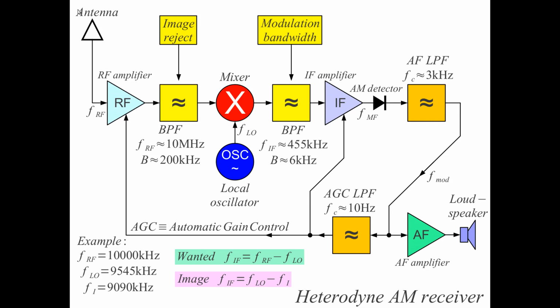So if the intensity of the antenna signal rises, the gain is automatically decreased, and this automatic gain control may be applied both to the radio frequency amplifier and to the intermediate frequency amplifier, so that the whole chain has linear amplification of the signal up to the detector, so that the amplitude modulation of the transmitted signal is not corrupted.